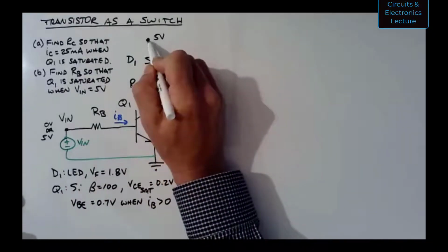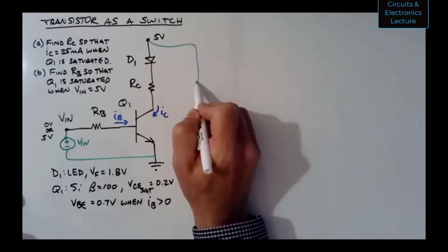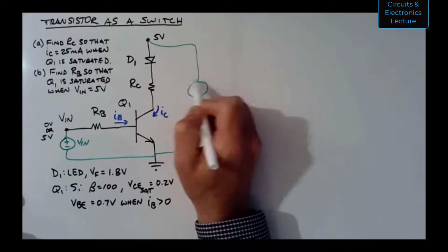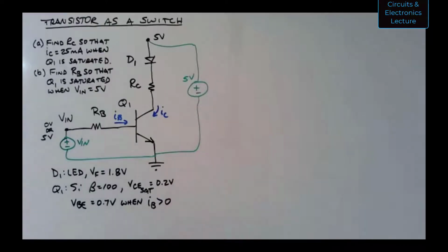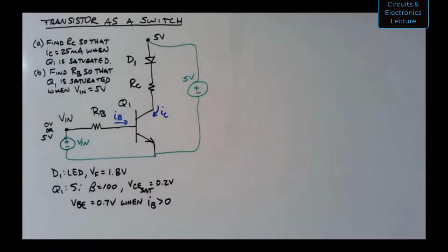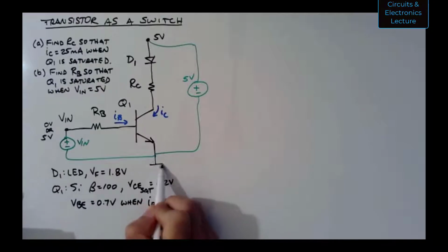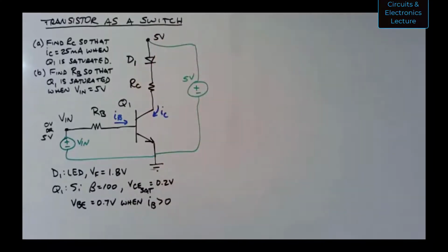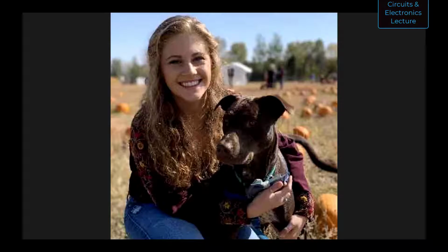And then the same thing here. I could draw a source right in here like this, 5 volts. So if I don't have any node voltages that I need to reference, I could delete this ground. I have not changed the circuit whatsoever because for all the node voltages, I've explicitly put in sources. But when I was using just Vin over here as a node voltage and 5 volts up top, I would have to put a ground there. Okay, that makes sense. Thank you. Sure.